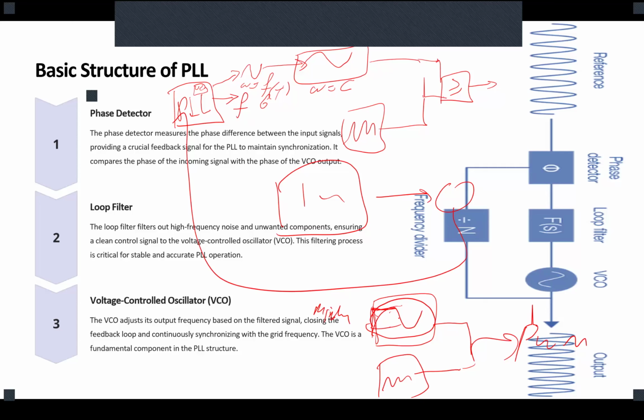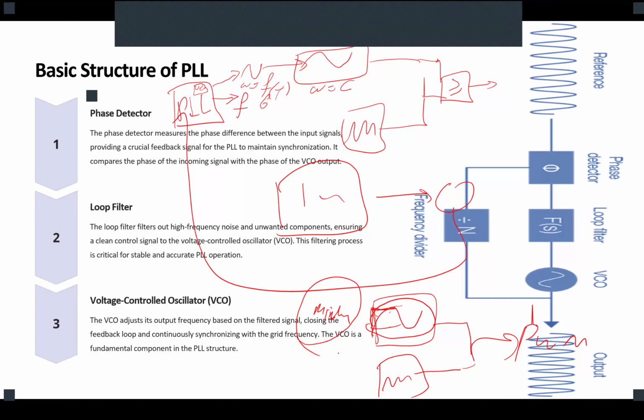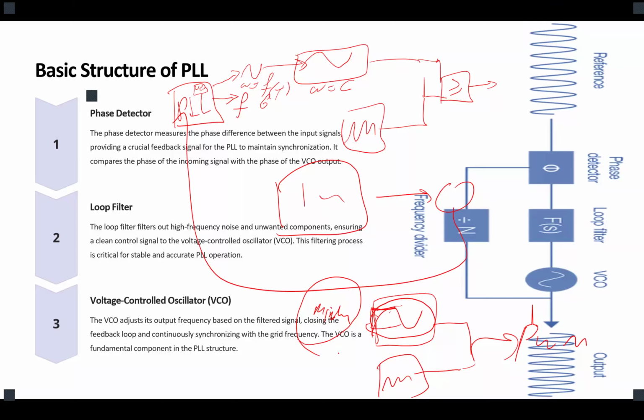By changing the theta of the reference signal, you're changing the theta of the output of the inverter, which means there is going to be a difference of theta between inverter and grid, meaning we have a flow of active power in some direction. Now, for control of the dynamic response to the grid, we control the modulation index and the theta of that reference signal. So that's what we control for voltage and current control. Are we good so far?